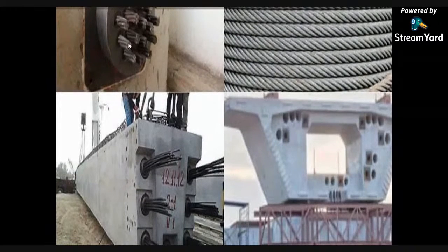This is termed as your strand, which is composed of 2, 3 or 7 pre-stressing wires. So this is your one strand, which is composed of either 2, 3 or 7 wires. Then there is a tendon, and a tendon is a group of either strands or wires. So this will be termed as your single tendon. Here in this figure you may just look, this is your single tendon, which is a combination of strands, and again in a strand there are a number of wires. Then cables are nothing but a number of tendons. So this total will comprise your cable.